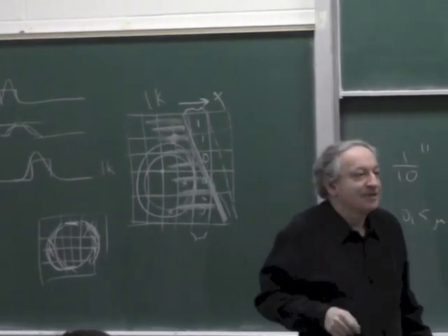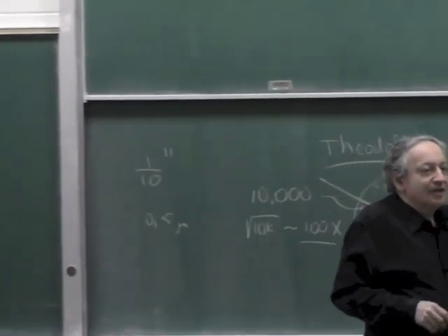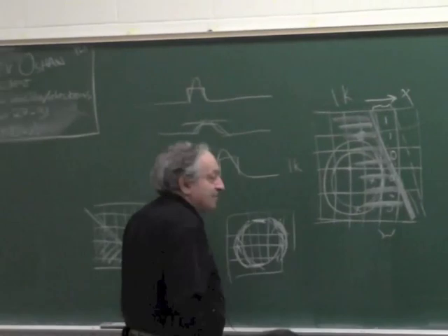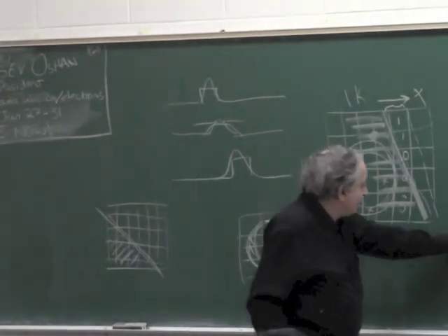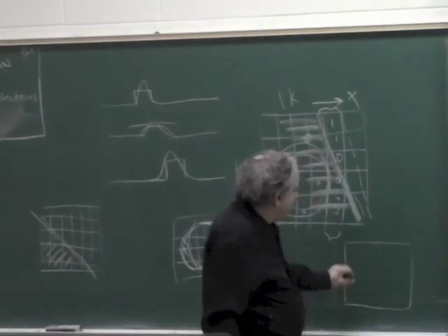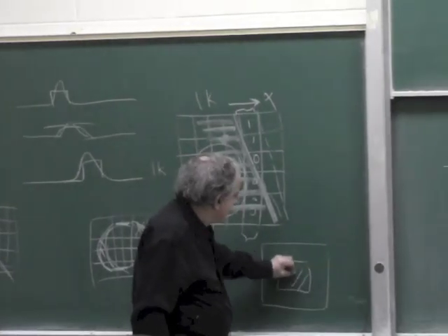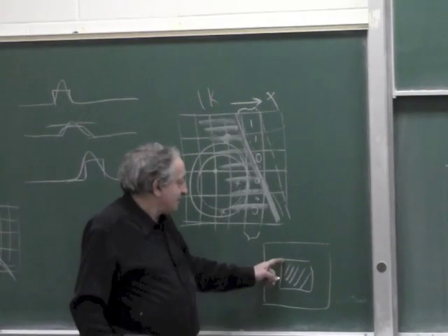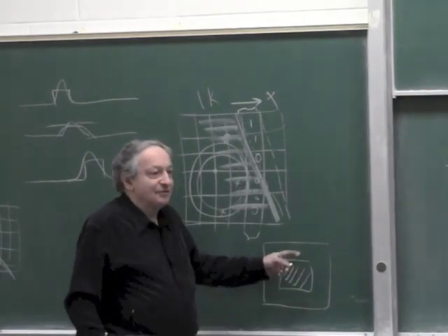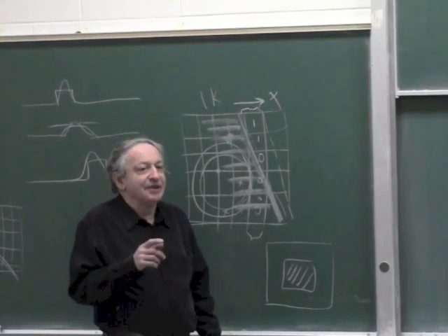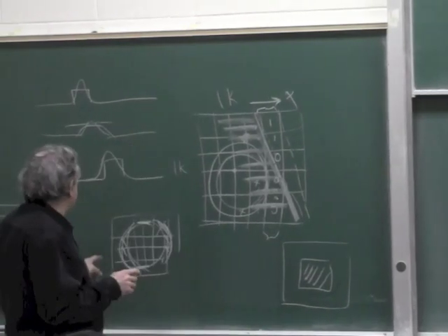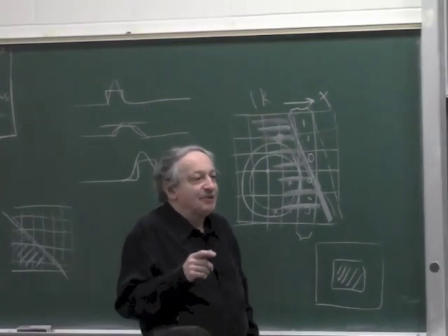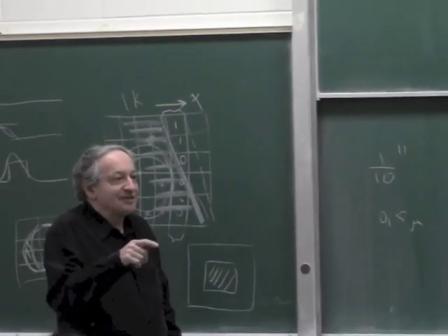Okay? Yes, please. Well, what about rotational movement? There's no problem to do it. You just need a target which is not rotationally symmetric. Because imagine if you had a camera and you projected a square, of course, you can analyze how much this end moves, how much this end moves, and you'll have rotation. And you realize right away that you can tailor this pattern to what you want to move to make the largest number of pixels change when the change you're interested in occurs.